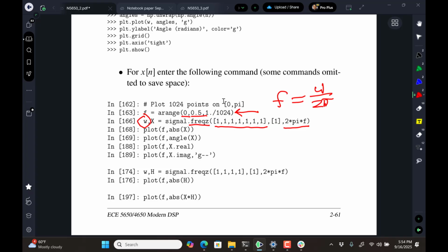You need to play with that when you're doing plots for homework problems. In other words, if you have it draw a picture of a frequency response and it looks kind of jaggy and not very smooth, remember that the Fourier transform of a sequence, if it's absolutely summable, is a nice smooth function in omega. It might have a lot of fluctuations in a narrow band, in which case you'll need to increase the resolution, but it should not look really hacked up. So I will write on homework papers a lot, use more points. Don't be so cheap. I mean, your computers are fast. Just draw a nice smooth function, because that's what it is.